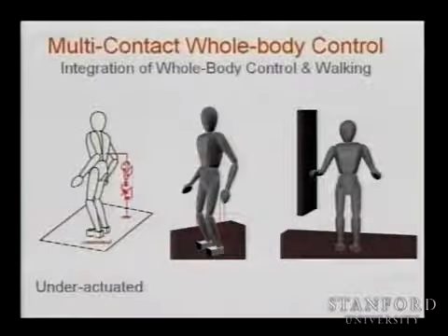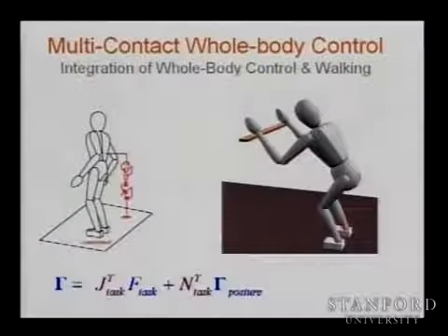The problem is very difficult, because when you are looking at a humanoid robot, you just push it and it will tip over. It is missing these 6 actuators. It's not connected to the ground. And you spend your time balancing. And if you have any reaction force, it will tip it over. So the question is, how can we move this body while dealing with those constraints? How can you do it?